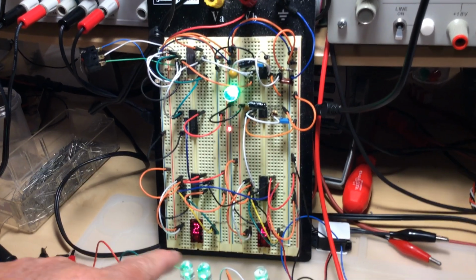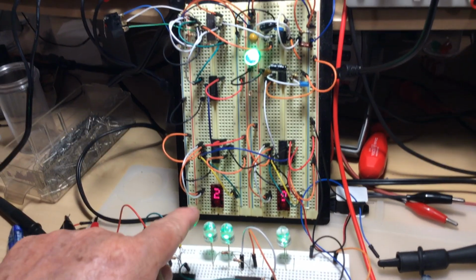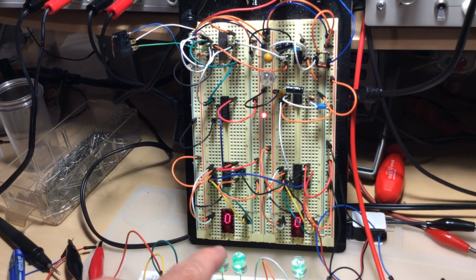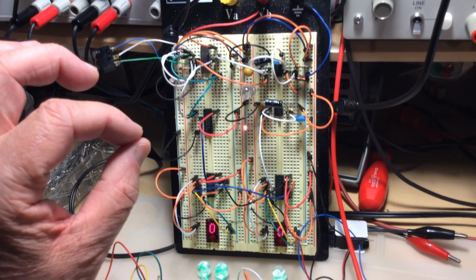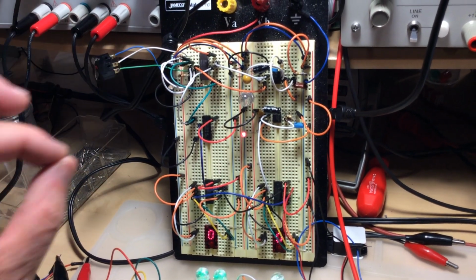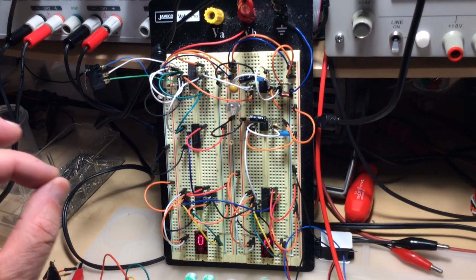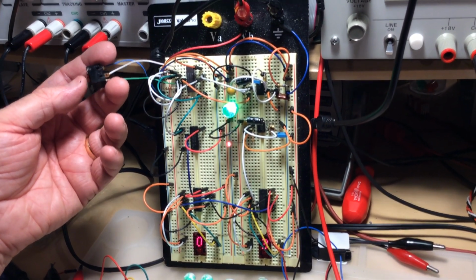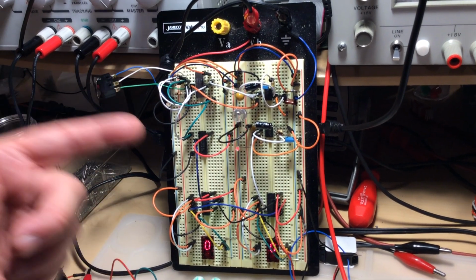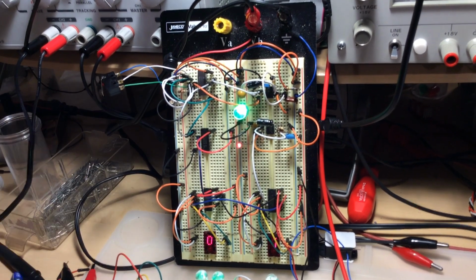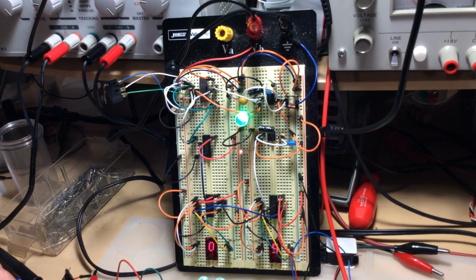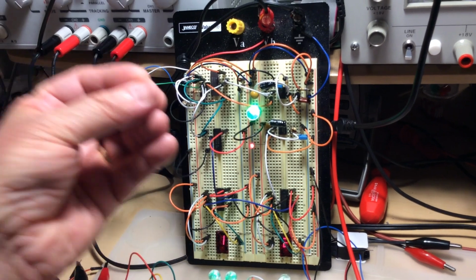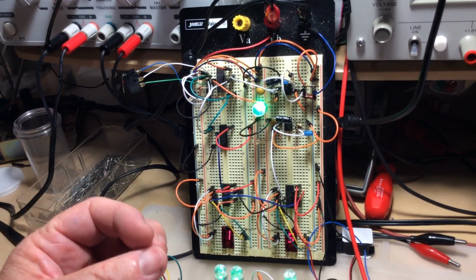So here, if I leave it one more time, at exactly 35 seconds, it's going to go up. 34, 35, you see? So at 35 seconds precisely, this circuit is reset. But after the 10 seconds reset, I'm going to leave it only for 5 seconds going on, and I'm going to reset it manually. 1, 2, 3, 4, 5. And I reset it. So this is the use of the gate OR. Either manual reset or automatic reset. That's an example of how can I control it.